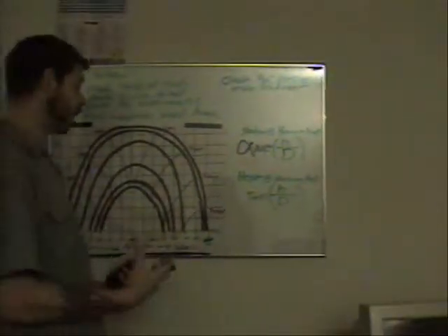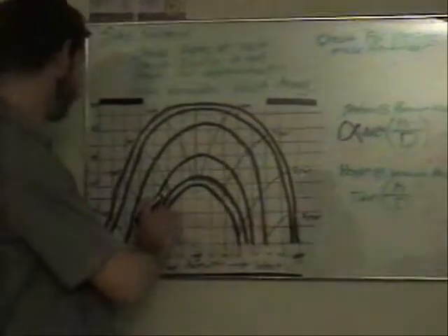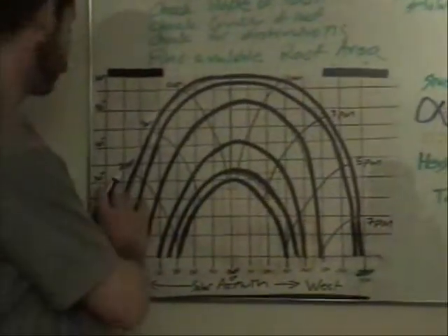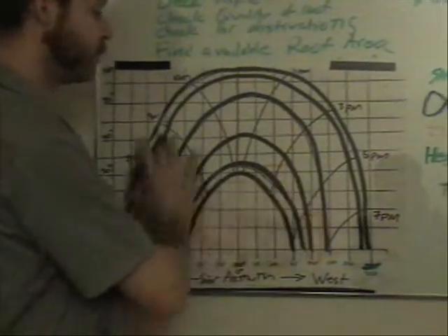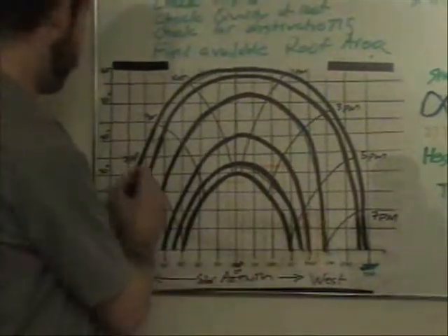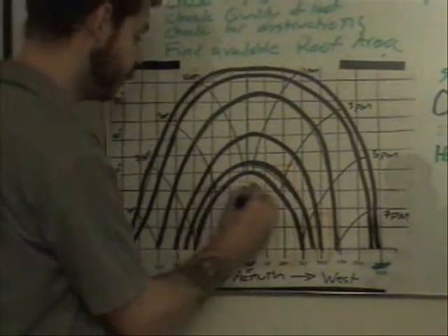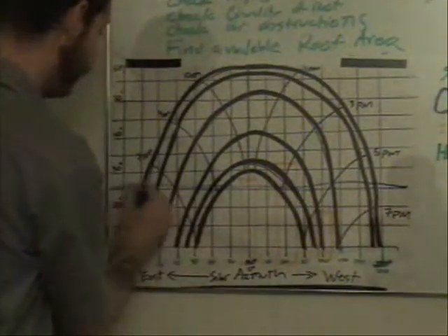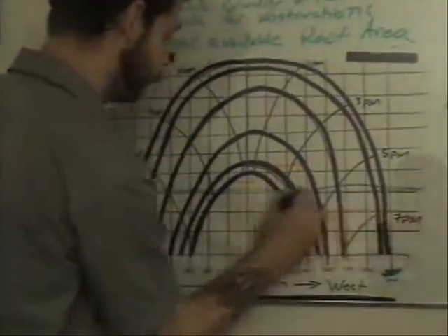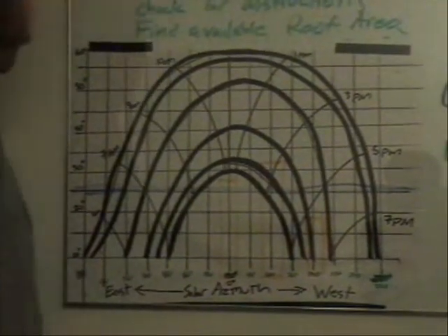The angle we're actually going to solve for is the angle that the sun is always above between 9 a.m. and 3 p.m. This is the solar chart for our area. Now, 9 a.m. is right here, 3 p.m. is right here. That is the angle we want to solve for. Okay? That angle is 25 degrees.